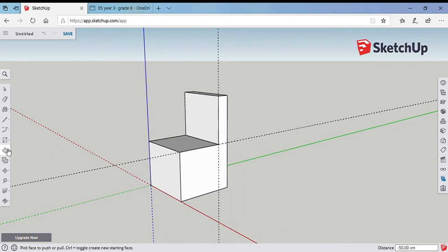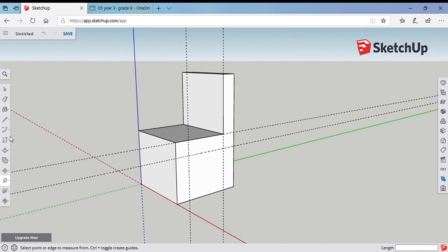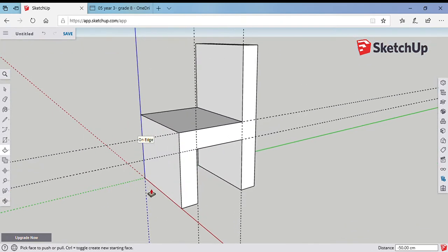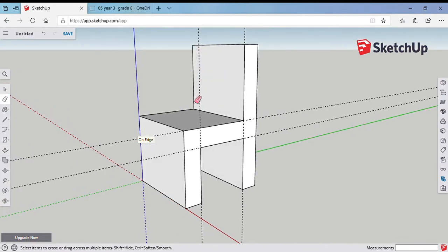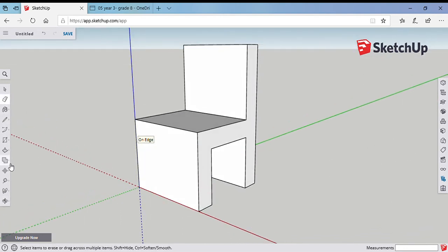Now I'm going to do the same for the rest of the chair. 10 again, and the thickness for the seat is 10. Again, I will draw over it and then use the push-pull tool to the end. See, it's gone. And in case it was not gone, you double check that you did it correctly, or sometimes only the surface on the back is left. You can select it using the select tool and hit delete, sorry.